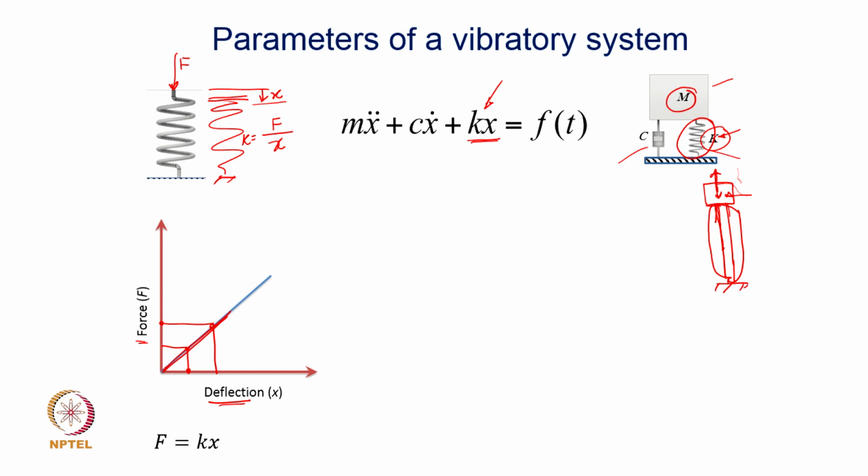And therefore, things become very easy for us because we are focusing on the vibratory deflection x of t, and no matter what x is, our restoring force will always be k into x. That simplifies the governing equation of motion, okay.